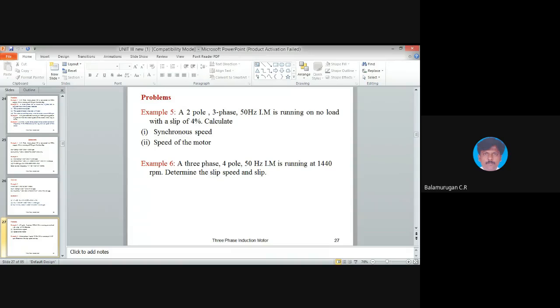Next, if we take the resultant here, this is phi r, and this angle will be 60 degree. If you write the resultant flux, we get again 2 root 3 by 2 phi m cos 60 by 2, so you'll get 1.5 phi m.